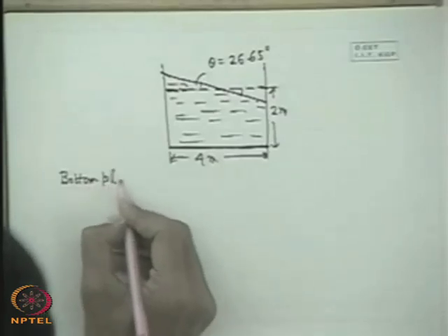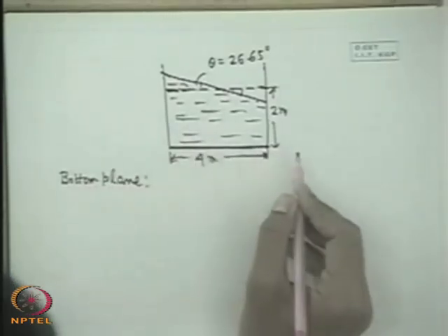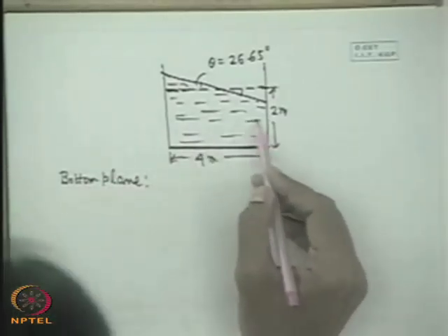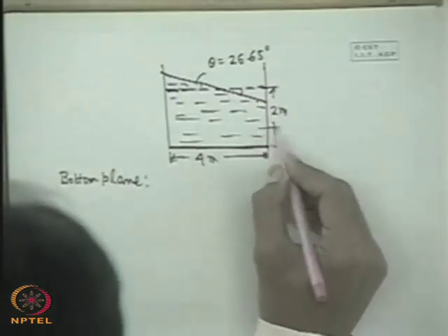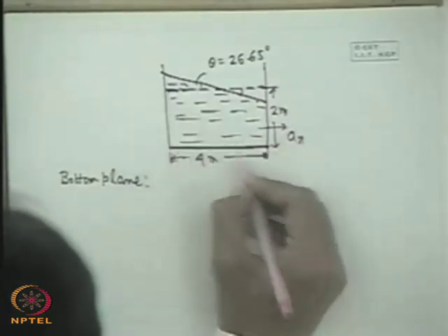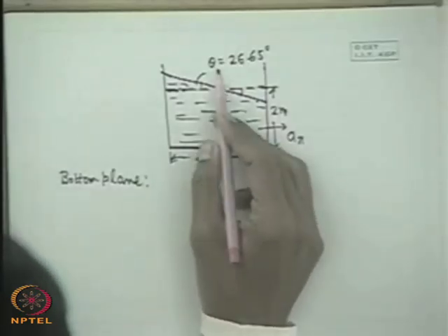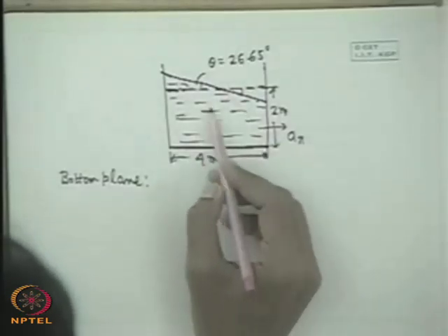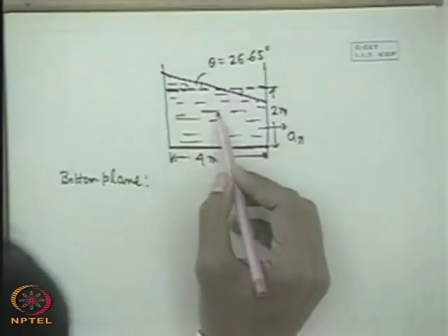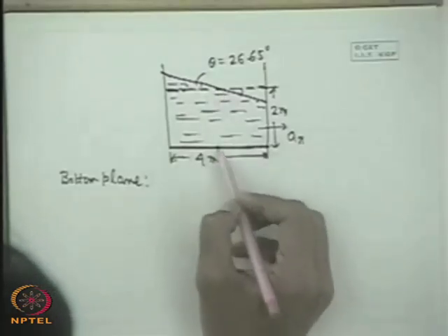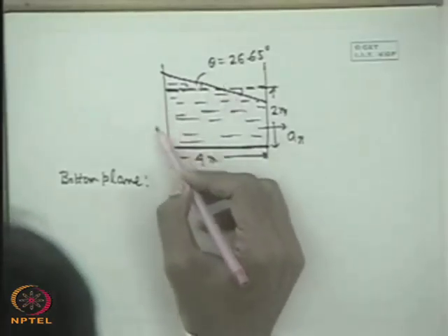Bottom plane is the, very good. So weight of the liquid. Whichever way it is accelerated in the horizontal direction, x, it doesn't matter, the total weight of the liquid will be the force here. But if it is accelerated in the z direction, then the force will be weight plus the acceleration. That means as if we consider g is increased by g plus az or minus az, downward.